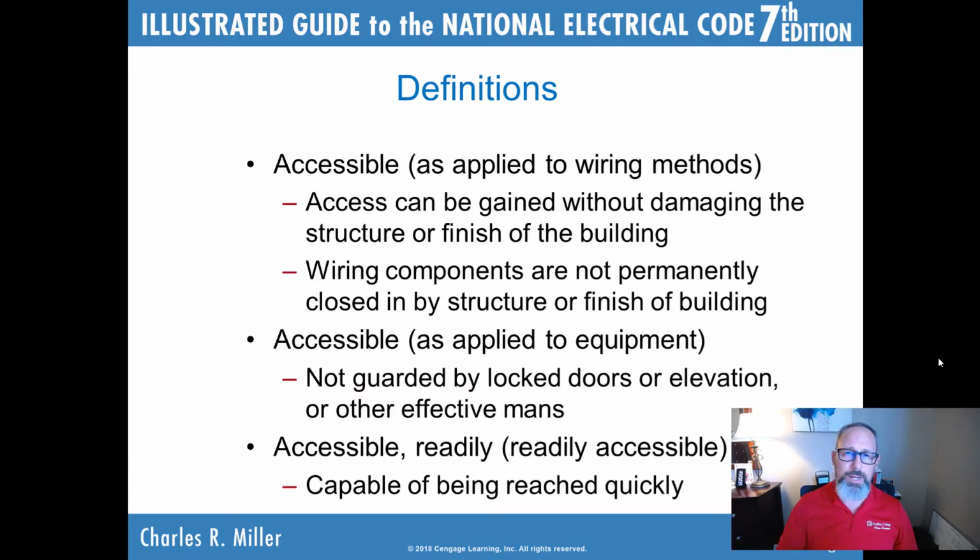And you put the junction box in the wall behind that. Well, once you put the junction box in and put the cover on it and walk away, and then the cabinet company comes in and installs the cabinets in that location, now you have blocked access to the box. And not all cabinet companies know that they need to drill a hole. So as long as you make it accessible, if you have a receptacle in a garage and you want to put a cabinet up, drill a hole in it.